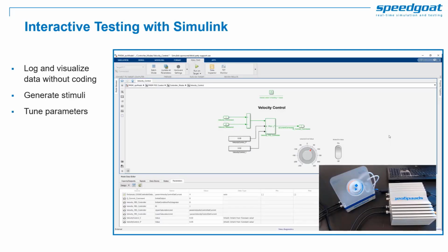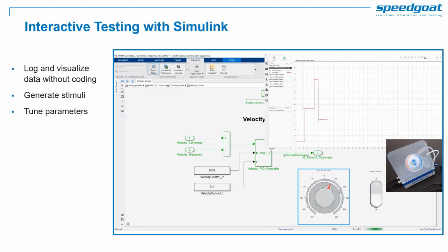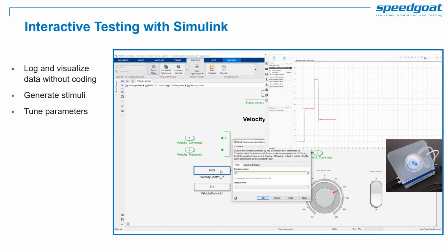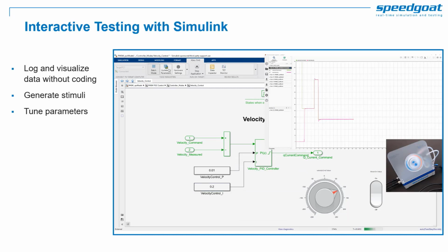Online tuning of parameters is a key requirement for HIL testing, and Simulink Real-Time allows you to do this in manifold ways. For instance, using Simulink dashboard components, from the Simulink Model Editor, or directly using the block mask. You can also update several parameters simultaneously using the batch mode. This allows you to freeze and unfreeze parameter uploading to the HIL simulator.